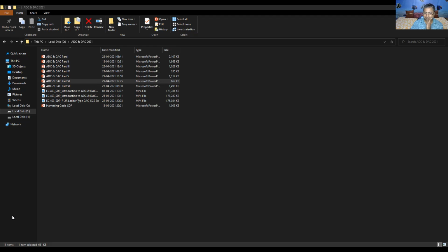Then the flip-flop is set as the logic input is 1. So then the Q will be 0, and the switch will connect to the minus VR, which is the opposite polarity of the input voltage. So at t is equal to t1, where t1 is 2 to the power of n into tc, then the v1 is minus 1 by rc v in into t, where t is equal to 2 to the power of n into tc.